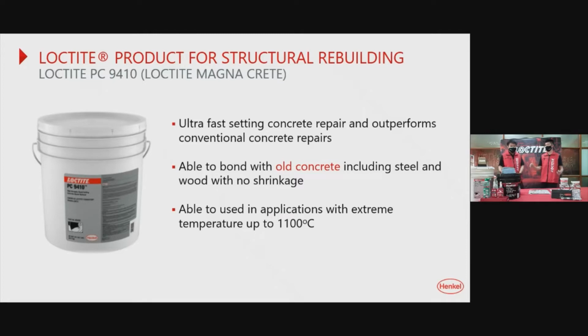The first thing is Magna Crete has ultra fast setting, or what we know as ultra fast functional cure. Just for your information, conventional concrete probably takes 36 to 48 hours to have a functional cure. But using this Magna Crete, in 1 hour it actually starts to dry off, and under 2 hours it reaches its functional cure already. So the difference between 2 hours and 48 hours of functional cure will help you reduce your overall maintenance downtime and